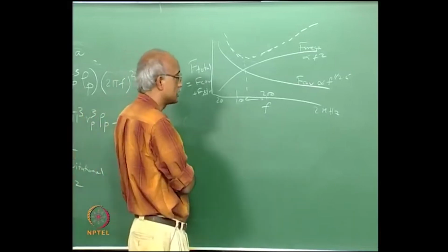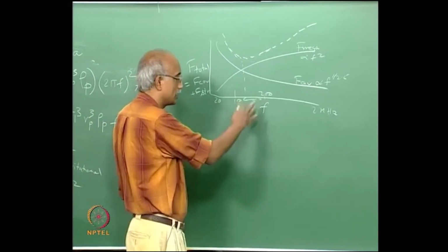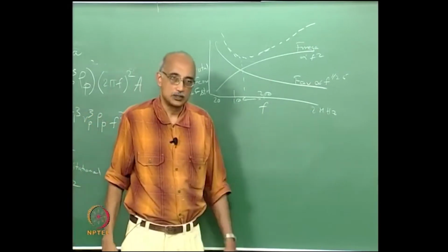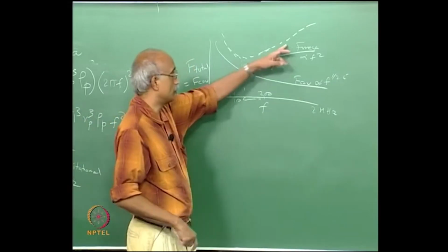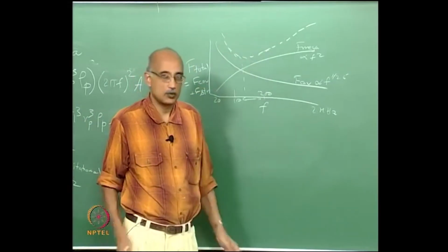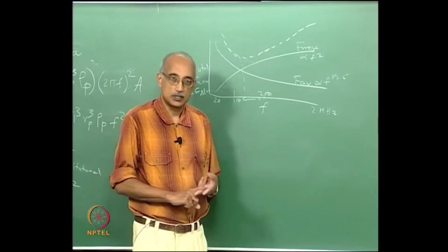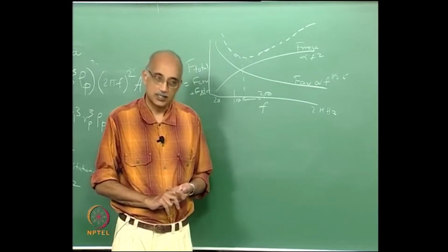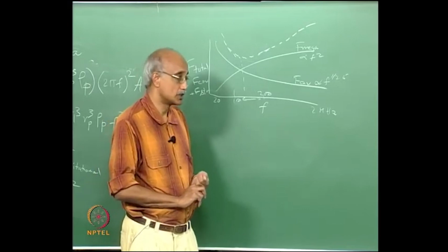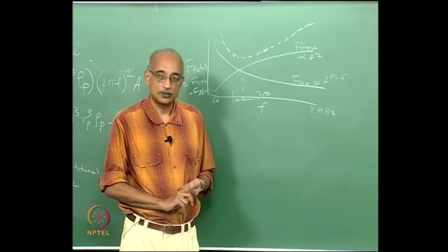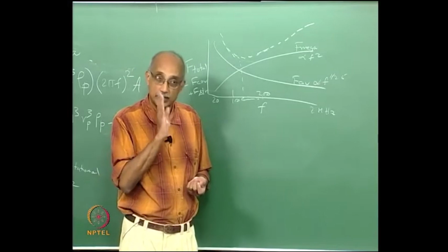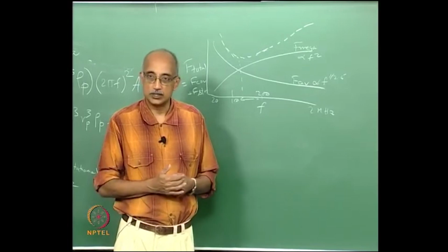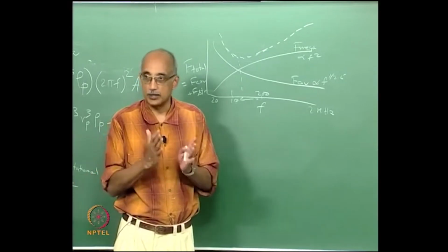So, the way I would use this is, I mean this would tell you that you should always use high frequencies, right, because if you are using a megasonic frequency, there is no surface damage and your cleaning force is just as good as cavitation. So, why not use it all the time? Two reasons: cost. Megasonic systems are much more expensive than ultrasonic systems. The second, and which is a huge constraint as far as particle removal, is that megasonic fields are unidirectional, they are not omnidirectional. Ultrasonics is omnidirectional. In other words, the force propagation is same in all directions.